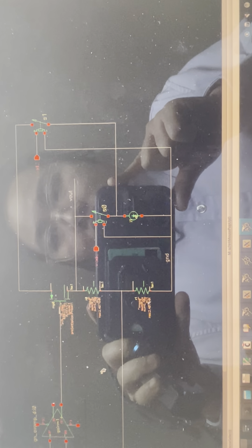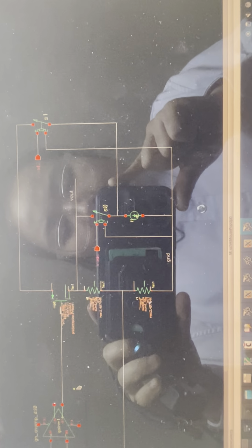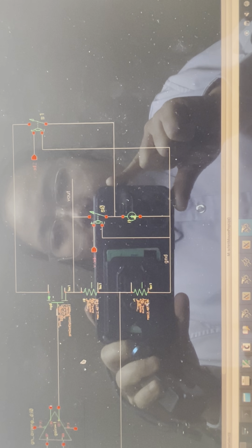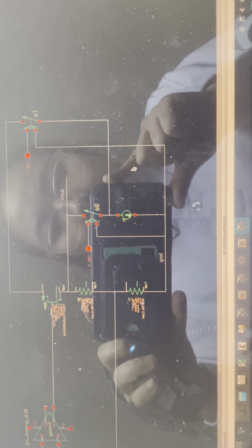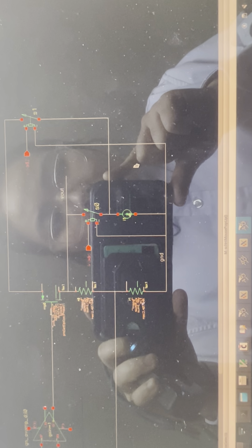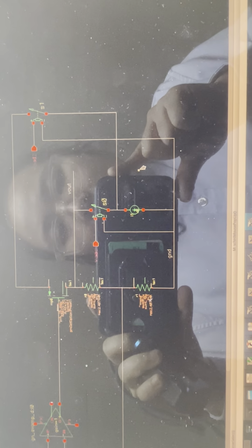If you take your circuit that you've stabilized at the moment, and without changing anything, you step a current load into it, you can start off with something like maybe 1 milliamp and see how far you can go.